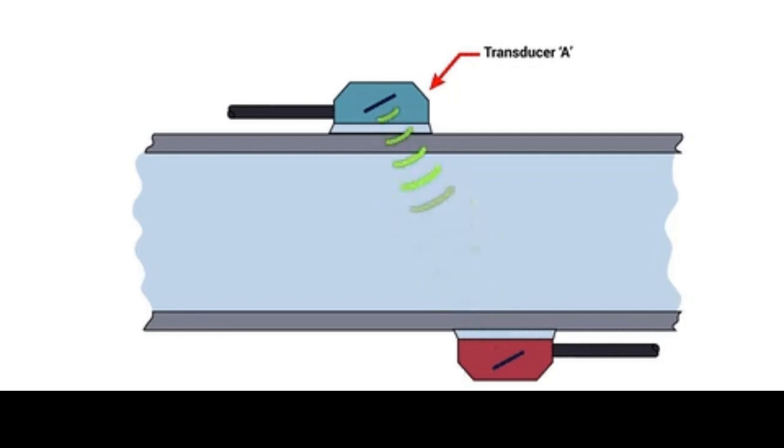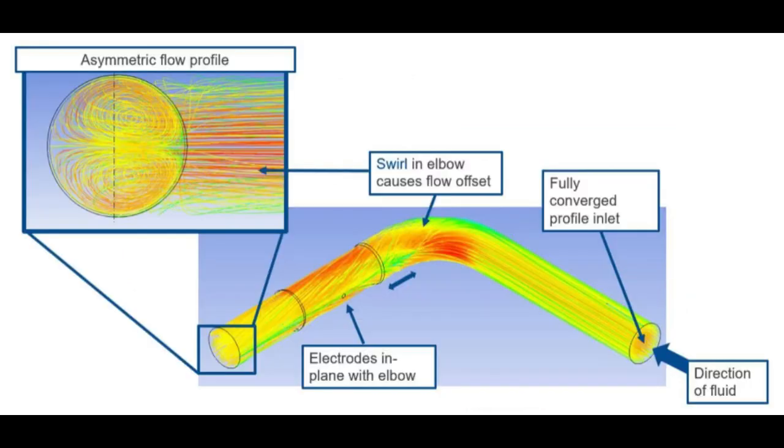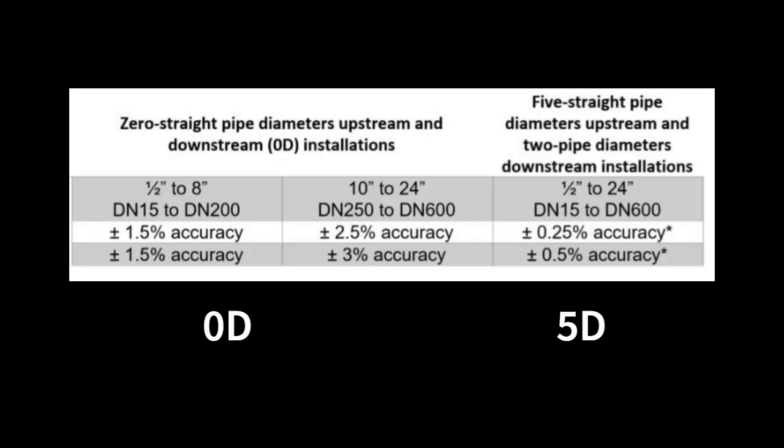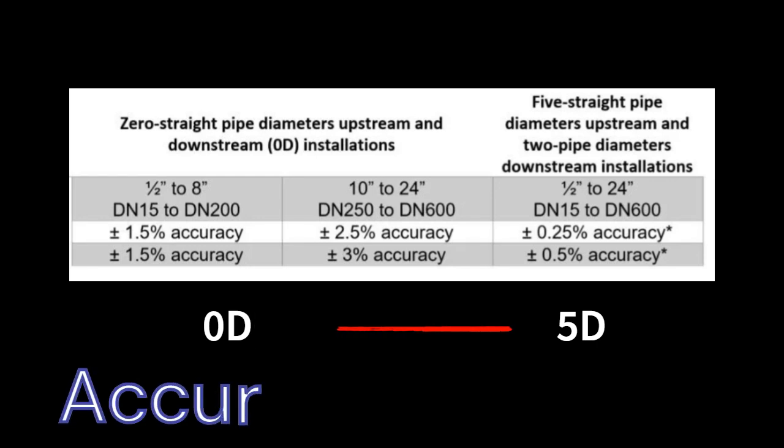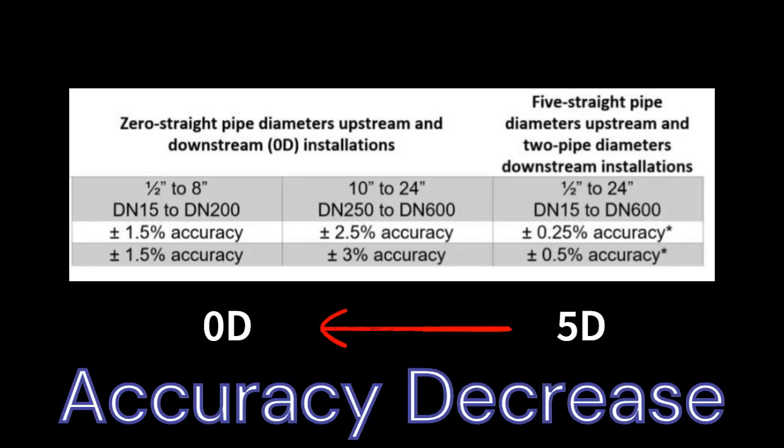3. Flow meter straight length. Lastly, for flow meters, the common error done by the design engineer is similar to non-return valve. However, there is an additional requirement on the downstream of the flow meter. Without sufficient pipe length, the accuracy of the flow meter will not be achieved.